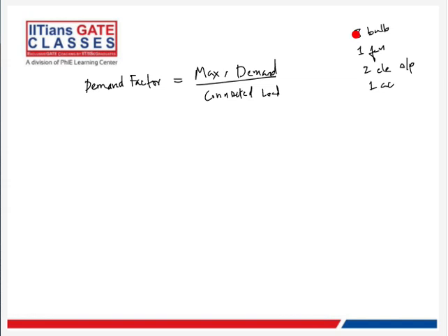So what is connected load? It is the total sum of all these devices' power ratings. So three bulbs at 60 each, say suppose you are using three incandescent bulbs. So that would be 180 watts, right? And you have a fan that probably is 100 watts, right? And two electrical outlets. You can connect many devices, so let's go for the maximum rating, which is 1000 watts, right? And one AC. It depends on what kind of rating you have. Let's put it at 1000 watts. I'm going for the maximum over here. So you probably have something like 2280. So this is the connected load.